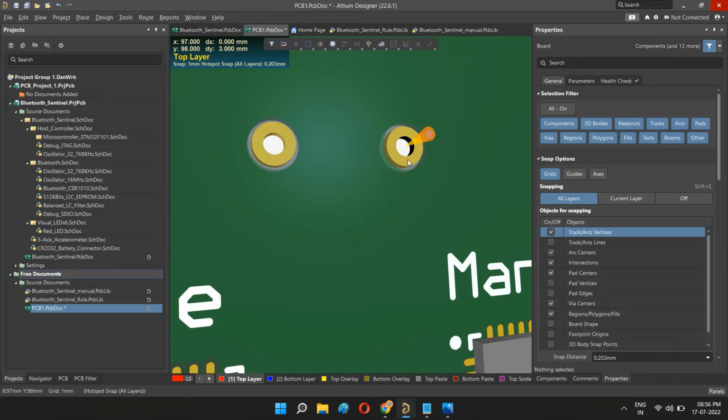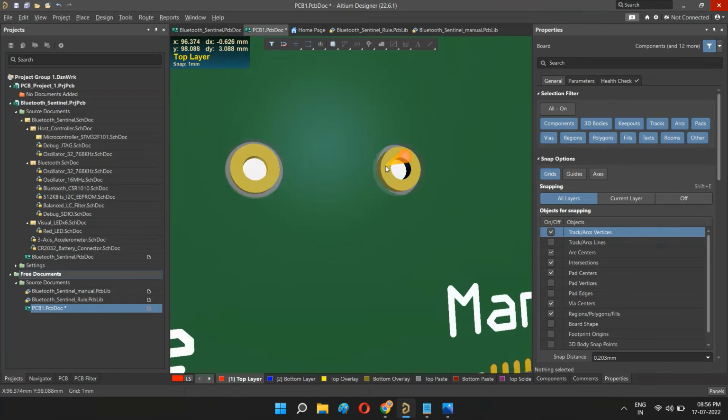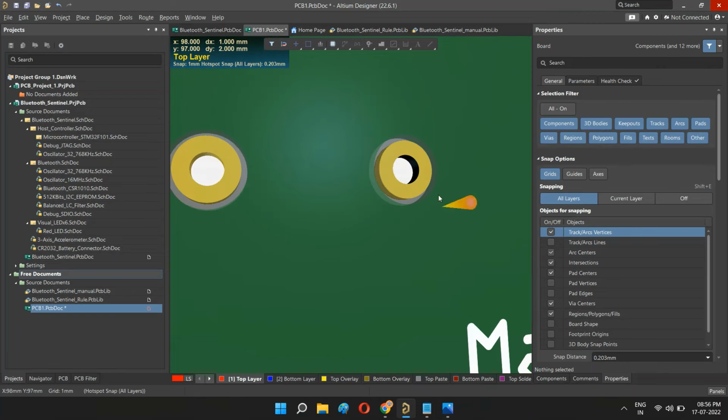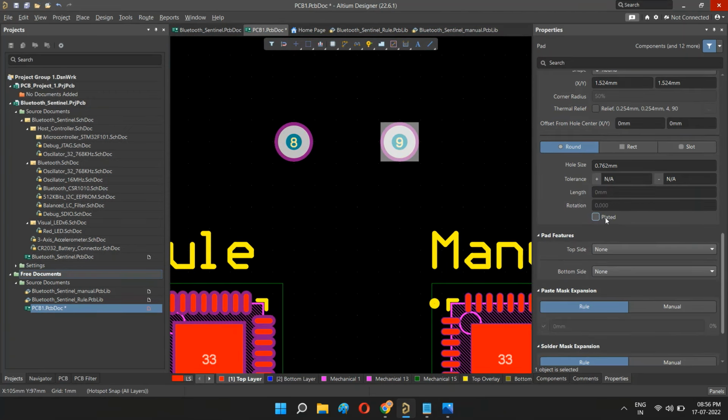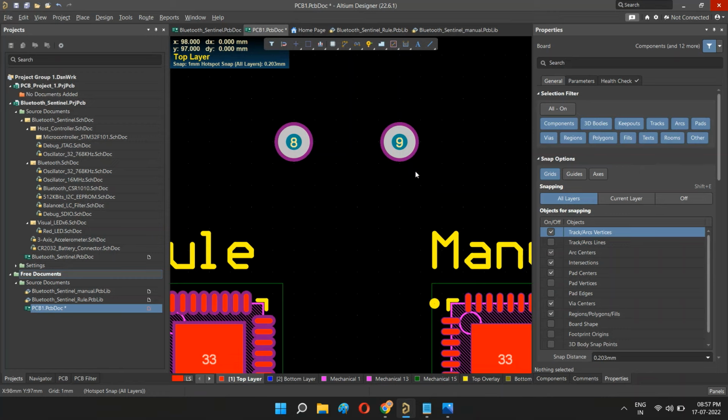In the 3D view, here also we can see this metallic ring, right? So we will think it is also plated, but actually it is non-plated. Always remember this. Whenever you create a through hole pin footprint, always ensure that you have checked this plated checkbox. You have to enable this always. Then only it will become a through hole conductive pad. So always use a plated pad. Always remember this before releasing your board, and always try to avoid this kind of error so that you can save your time and you can save money also.